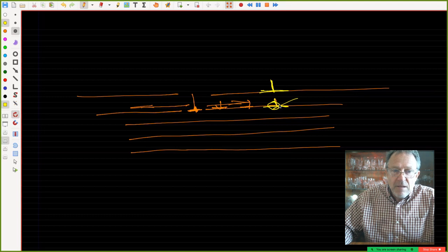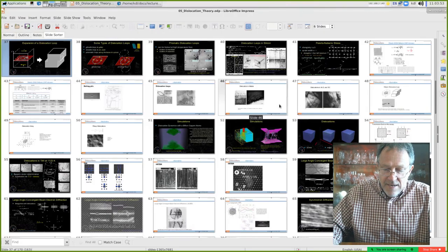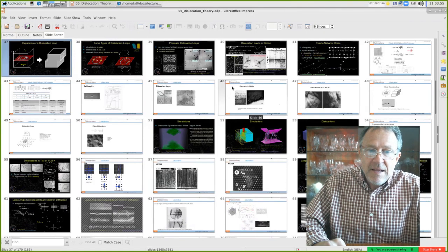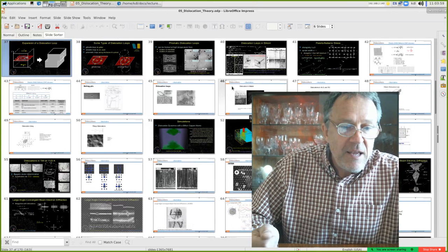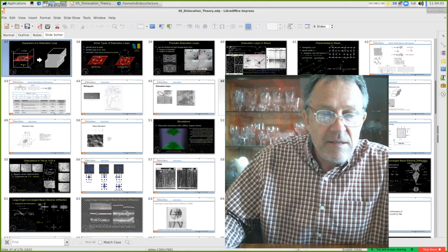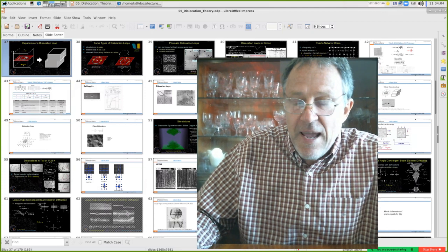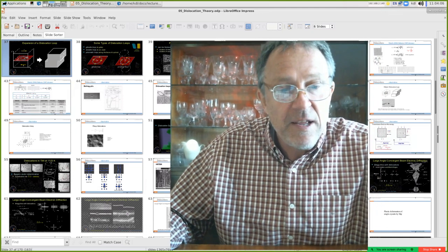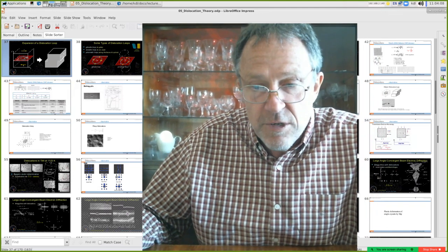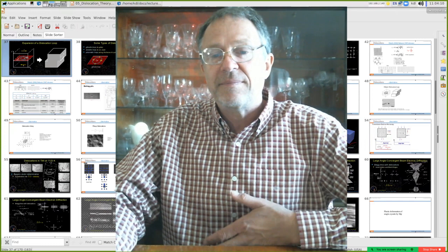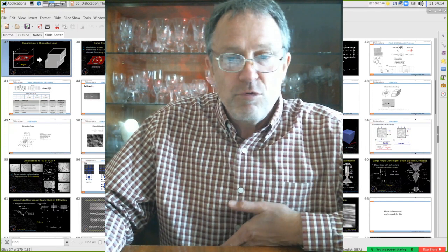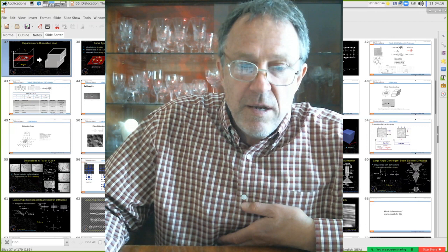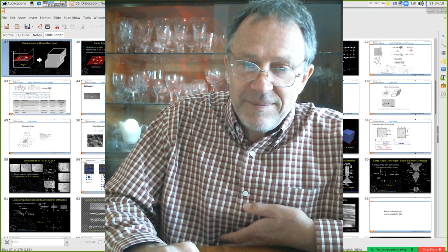But we can go to another slip plane, and that's a fundamental difference between the two types of dislocations. For the one we need diffusion, add and remove material, that's why it costs work, it costs energy. While for slip it is non work consuming.